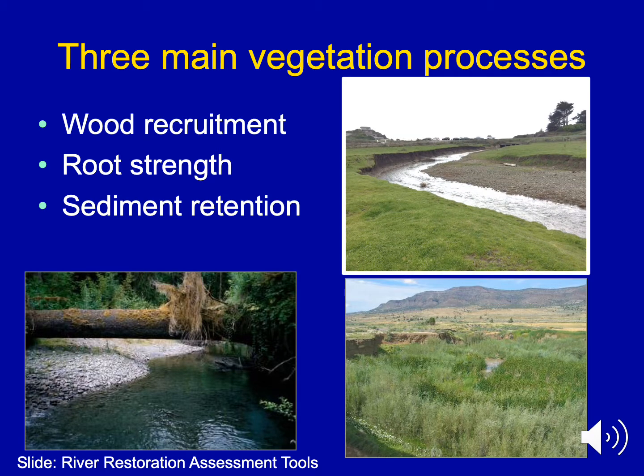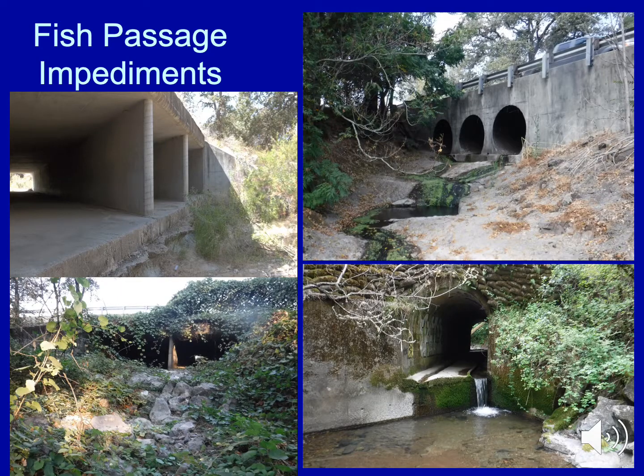When you don't have vegetation, you often end up with something like this, or if you had a system that evolved with vegetation and then you remove the vegetation. This is a grazing example on the central coast, near Bodega Bay. Caltrans is looking at, right now we're designing a new crossing right here, but there are obviously issues up here that have changed the natural channel shape and morphology. It's over widened, with a lot of sediment depositing out. So as part of fixing this crossing down here, there is going to be a lot of re-veg work happening upstream as well.